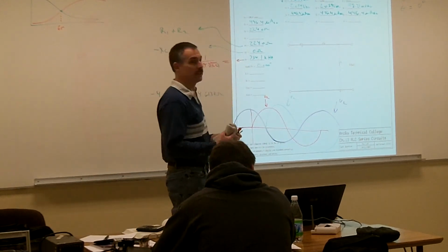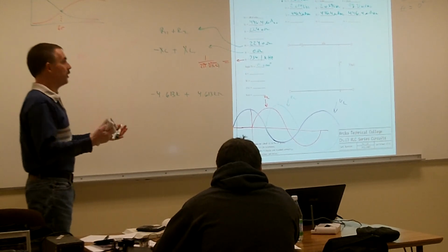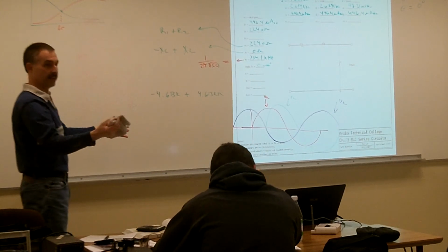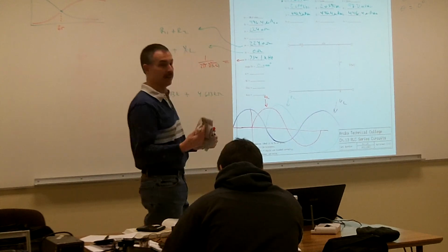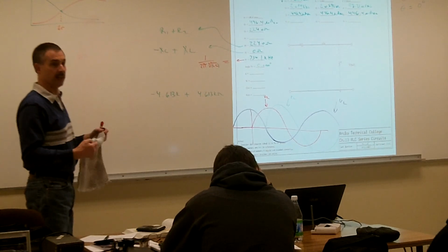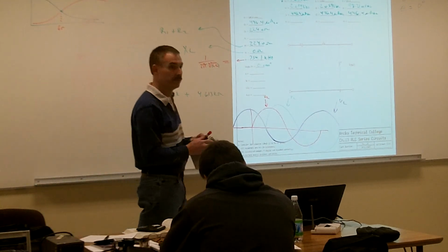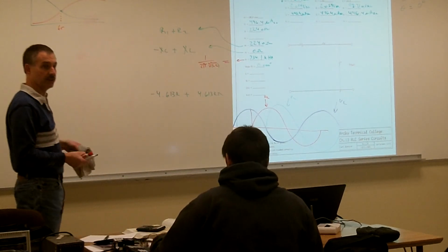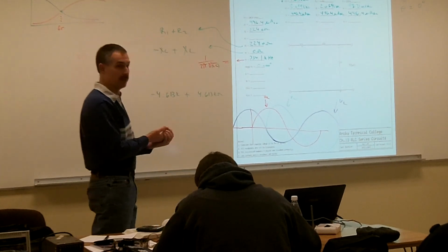And typically, in most cases, depending on what our signals are, like if we're doing radio signals, because if I'm going to broadcast a radio station, I'm trying to output a bunch of power. So we already know that that's always going to be an RMS value because it's power. It always has to be related to the power. So we always make things easy on us and stick with the RMS value. On audio circuits, a lot of times they are already RMS values, especially on the output stages, because that's the power coming out of our antenna, and that power has to be calculated using an RMS value. But if we're doing just basic signals, then it could either be a peak or peak to peak.